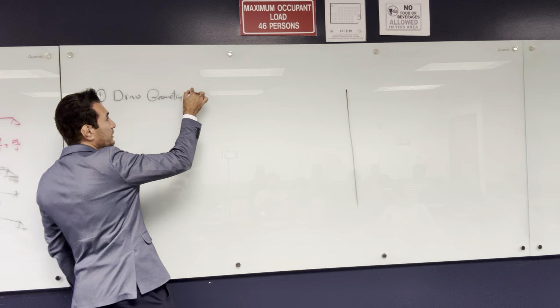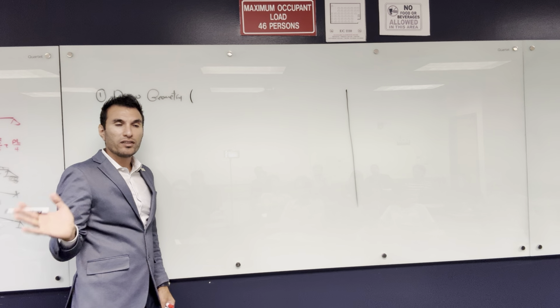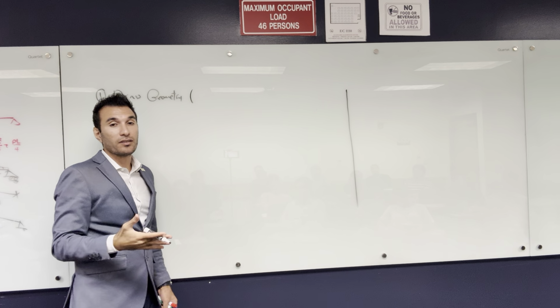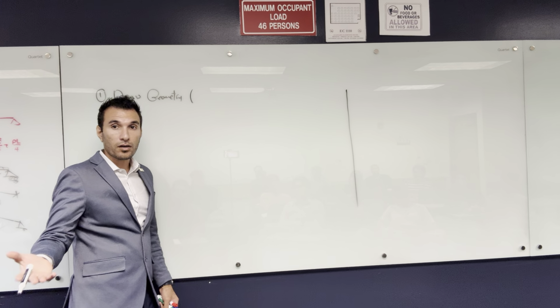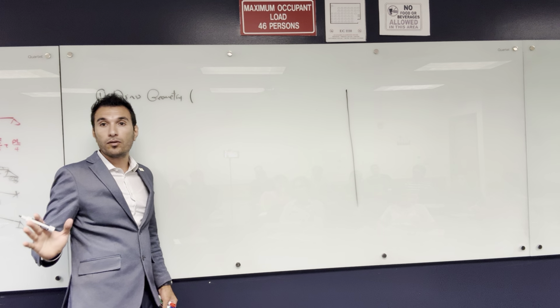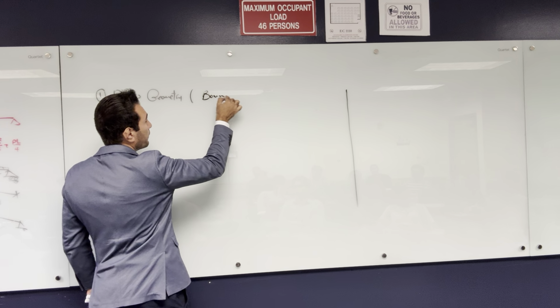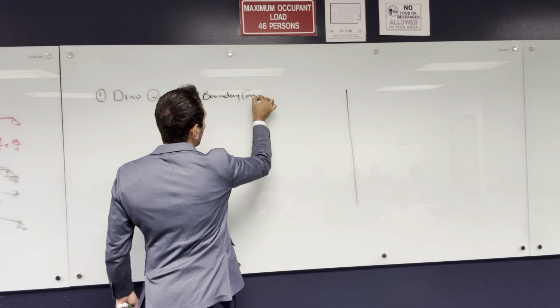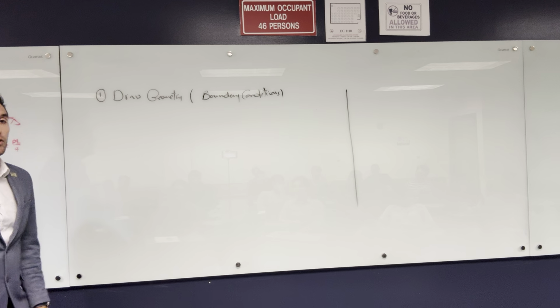So in the geometry step, you have to define boundary conditions. Once you import your structure, you have to tell the software, is this foundation fixed or hinged? Is this a roller, or is this a guided support, or is this a hinged support? So you have to define the boundary conditions. Okay, that's in the geometry step.